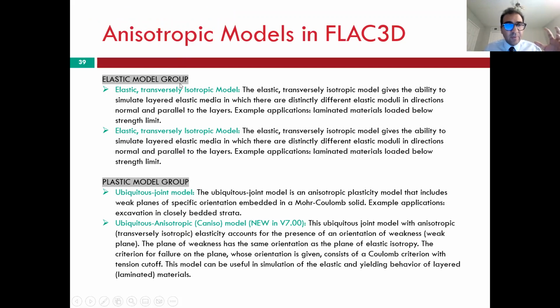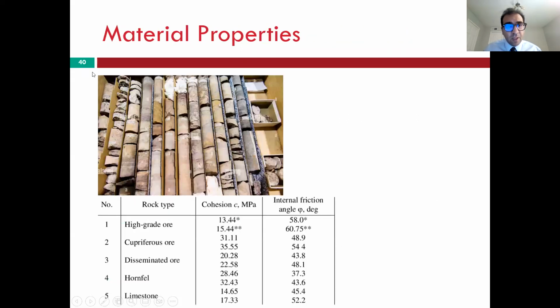One of the interesting things that we mostly deal in geomechanics simulation, specifically for unconventional reservoirs, is the problem of anisotropy in the behavior of the materials. So in FLAC and UDEC, we have options for constitutive models that can simulate the anisotropic systems as well, in both elastic and elastic-plastic condition.